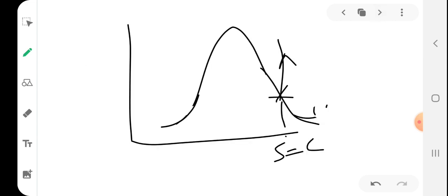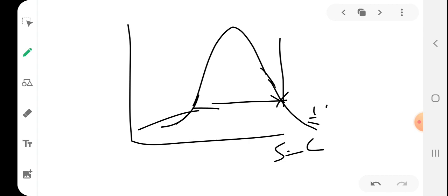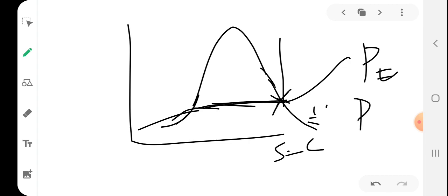So did you understand? Actually, this is the evaporator, and this is the compressor. So the actual suction pressure inside the compressor should be slightly below that of the evaporator. So this is the evaporator pressure, some evaporator pressure, and at the inlet of the compressor, the pressure would be the same, PE.